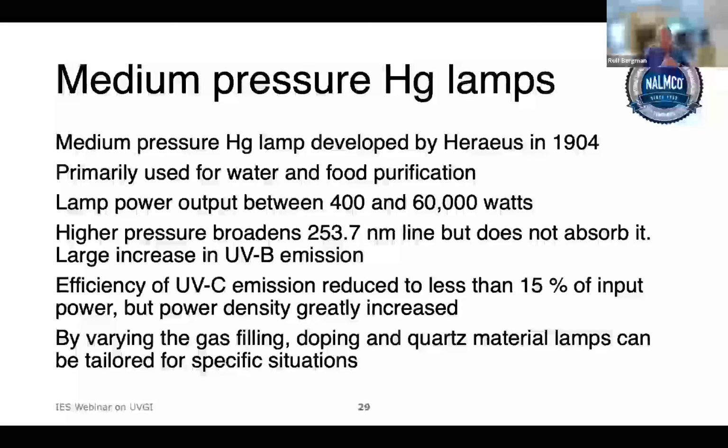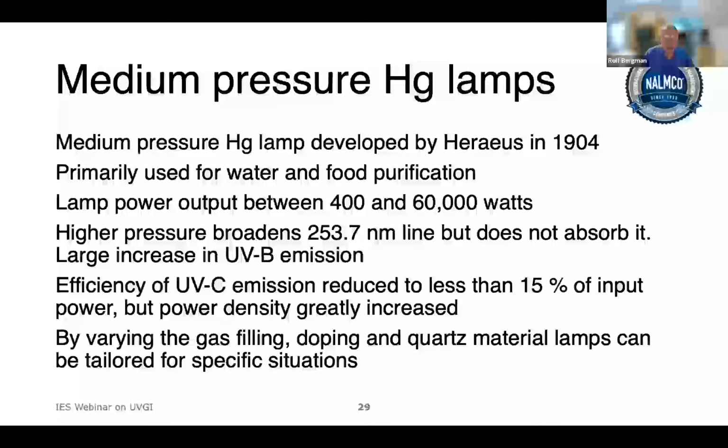But because you can put a lot more power in, as I said, 200 times more power than a fluorescent lamp for the same length, the total UVC power generated is much higher, and therefore that is a benefit. You can also modify the gas filling, the doping, and the quartz to tailor to specific situations.